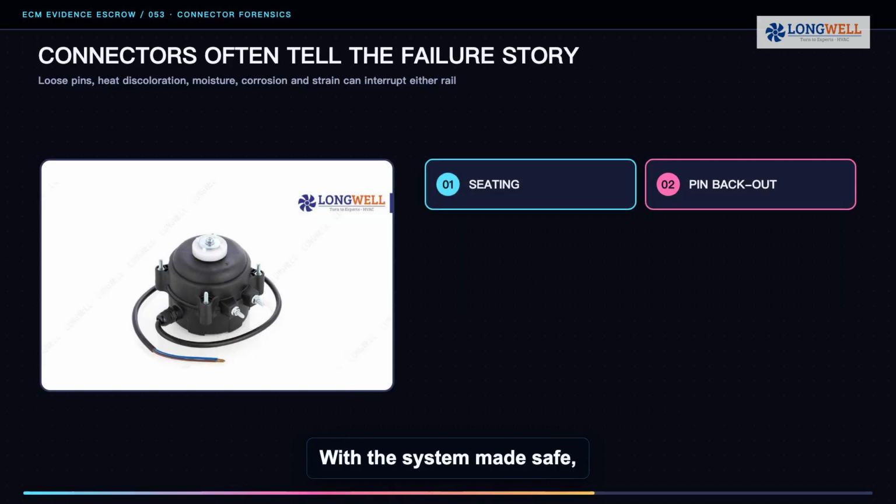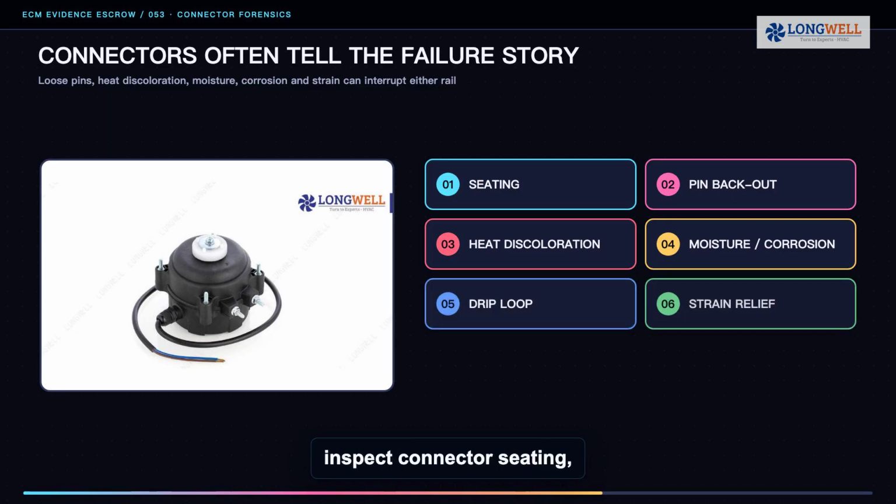With the system made safe, inspect connector seating, pins backing out, heat discoloration, moisture, corrosion, drip loop routing and strain relief. A damaged pin can remove power, reference, data, or feedback intermittently and mimic an electronic module failure.